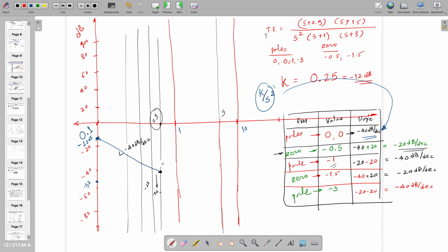So Nakul, from this point, it's 20 dB down, right? And 1 decade ahead, that is exactly happening at 5, right? So this is 1 decade and this is minus 20. Connecting these 2 points with a scale, you can draw better. Minus 20.